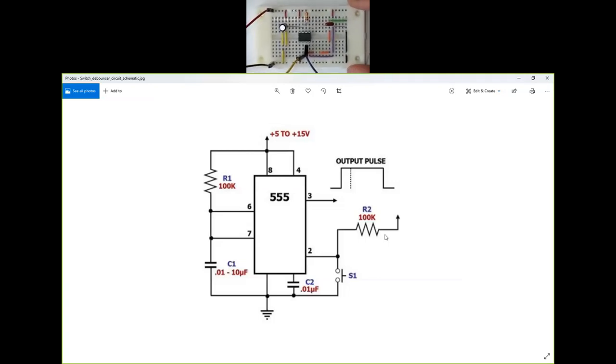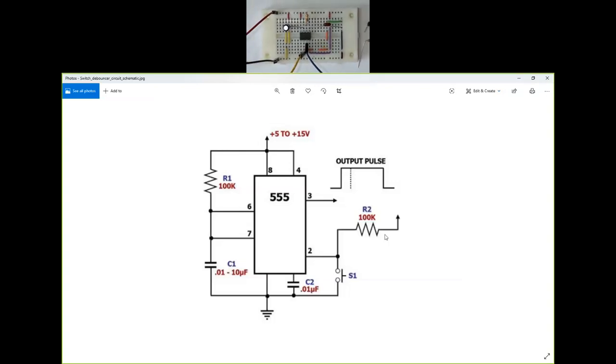Many things that you might see are sort of a repetition of what you saw in the astable mode of the 555. Okay, so let's bring up waveforms and see if we are able to measure things. To make sure that I measure both the bounciness or the fake bounced data as well as the clean output, I'm going to place two channels. One channel, say channel 1, I'm going to place on pin 2, the yellow wire.